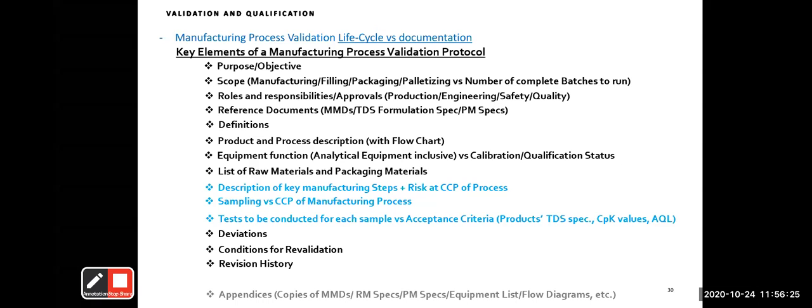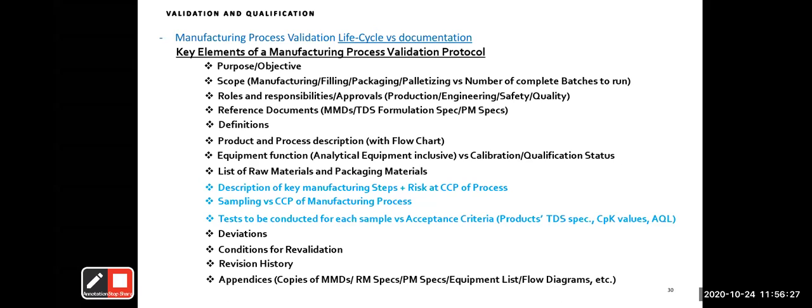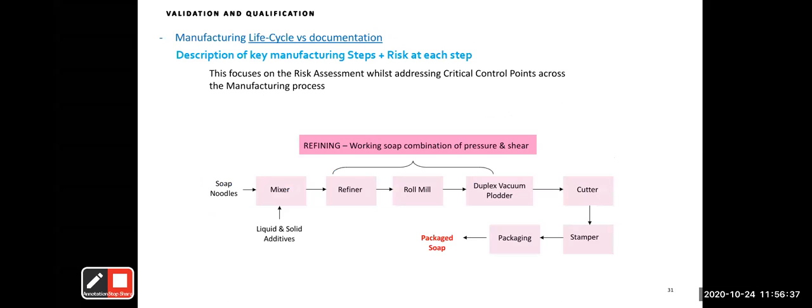At the top, you might get a 4.9. At the middle, you might get 4.95. At the base, you might get 5. You now define your own acceptance criteria to confirm whether this mixing is homogeneous or not. So you use something like your RSD to confirm whether that mixing was homogeneous or not.